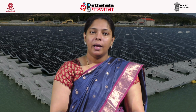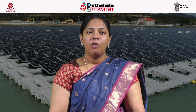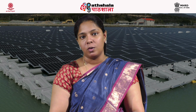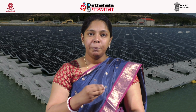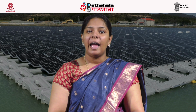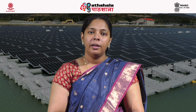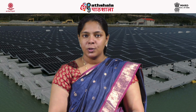So to conclude, in this module, we have discussed the solar pond. What is a solar pond? It is an artificially constructed pond. Sometimes a natural pond can also be used for the collection and storage of solar energy. Here, it prevents the convective currents so that the trapped heat is not lost. We have seen different types of solar ponds, like non-convective and convective. Under non-convective, there are two types, salt gradient and membrane type. The most commonly used one is the salt gradient solar pond.